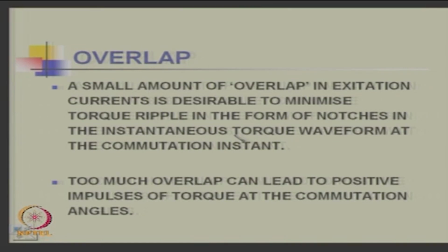So, what is done is you have to think of optimizing the switching of the currents in the respective windings and also calculate the torque and then find out how to minimize the torque ripples, because unlike all other machines, where you can have an induction machine which gives a constant torque continuously, you are happy. Here it is like you are just pushing torque in pulses. So, that is the problem of switched reluctance motors, because you are just banging the torque. So, the shaft is getting pulsed torques.